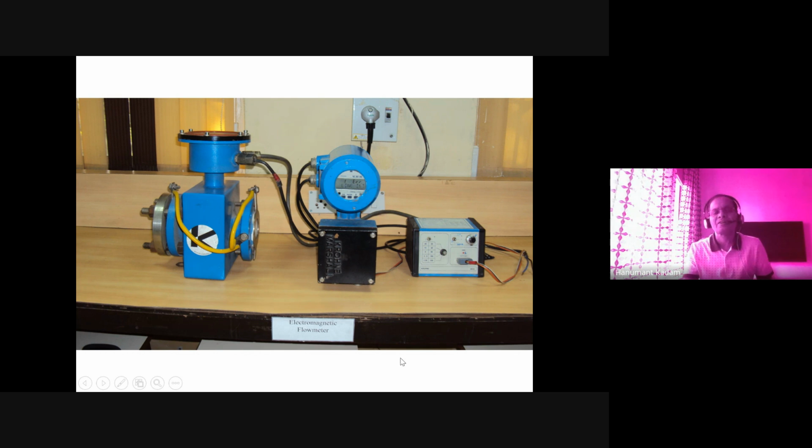Later on, you can learn further about how it is maintained. And mostly in the process plant, what happens? Suppose the plant is nitric acid, or any fertilizer, NPK fertilizer. So the people are busy in the plant. If the flow meter is not working, they understand the readings are not as per their process requirement, then they remove it from the line and send it to the instrumentation workshop. And these setups are available in instrument workshops, and that I am demonstrating here. So what are the setups required for calibrating a transmitter?